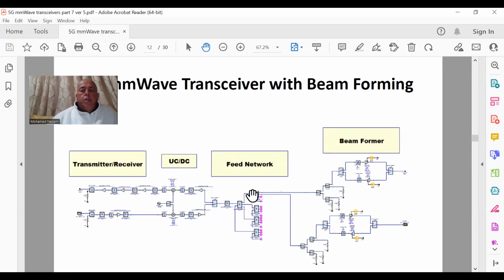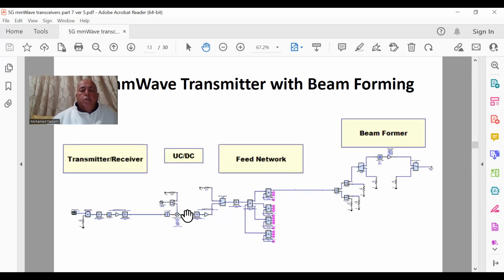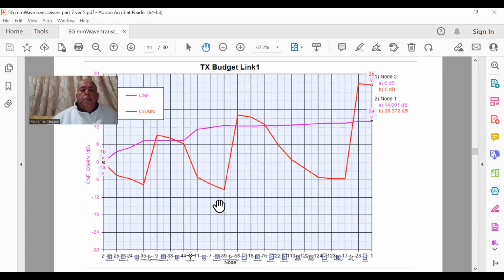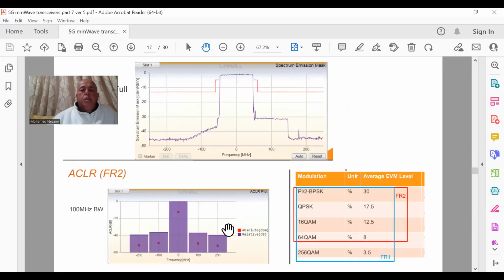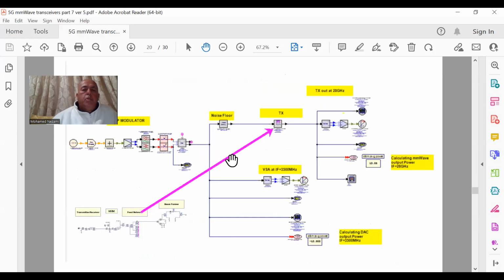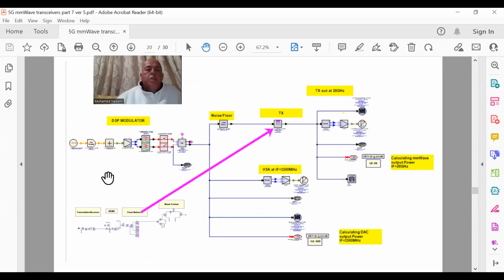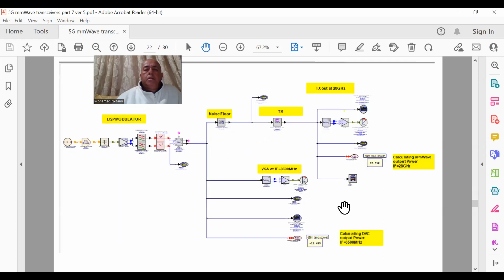I took the transmit path only, ran the RF, and then did the analysis on it theoretically just to make sure. And then we went into the SystemVue digital signal processing section and added an actual modulator, grabbing bits, ones and zeros all the way, and tracing the signal through the whole chain to validate the system.